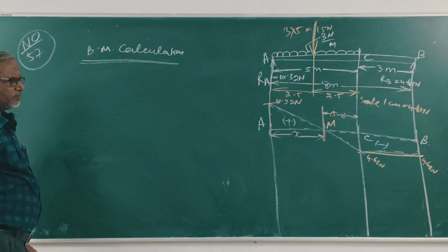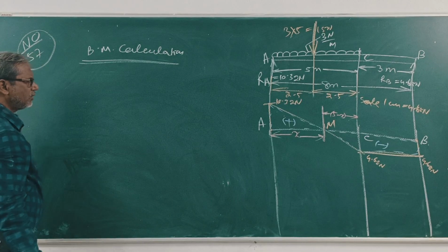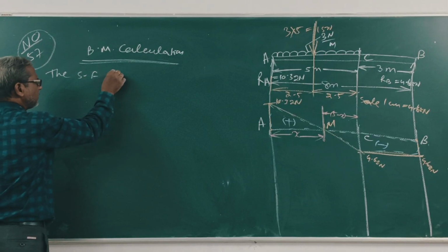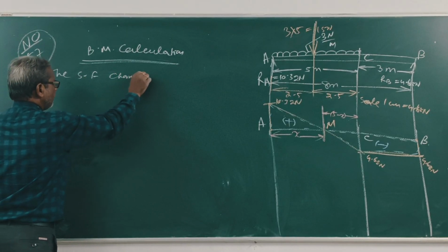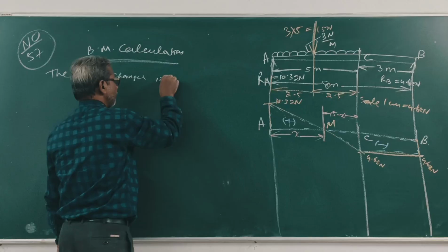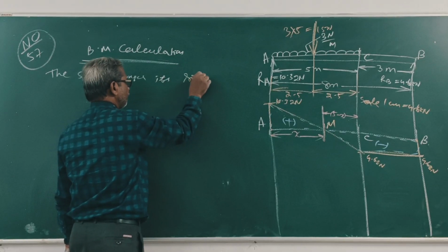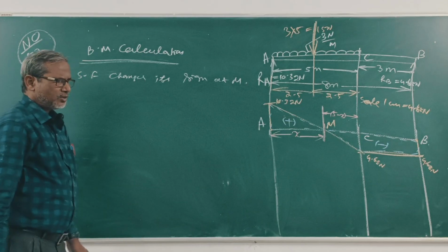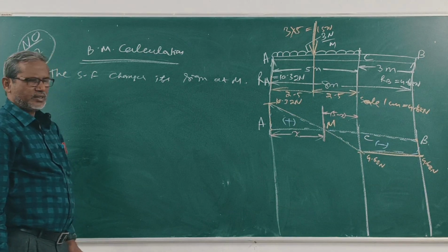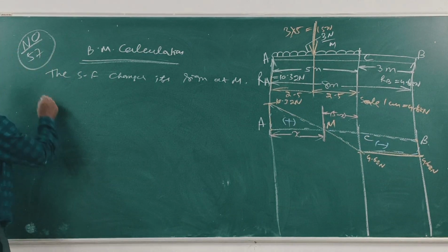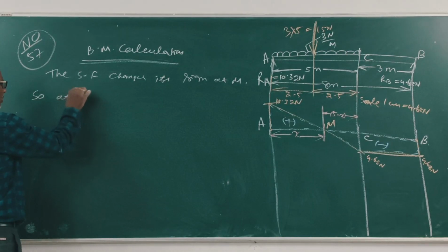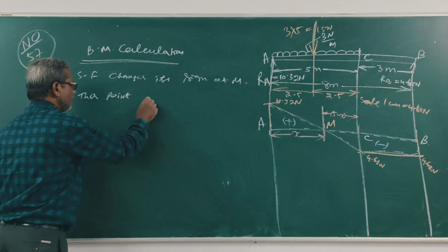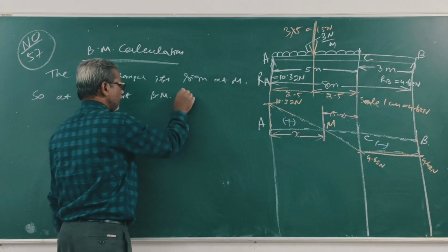Clear? The shear force changes its sign at M. So at this point, the bending moment is maximum.